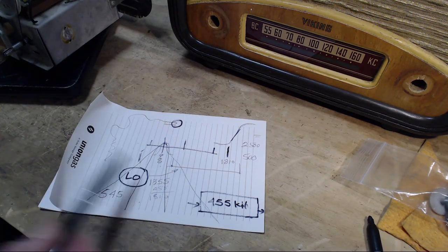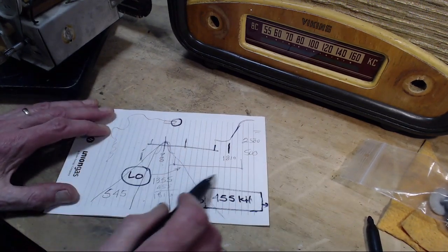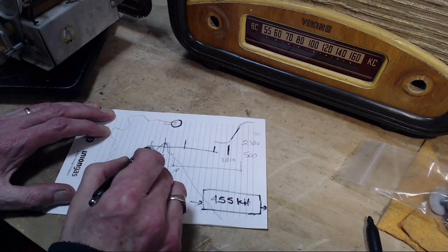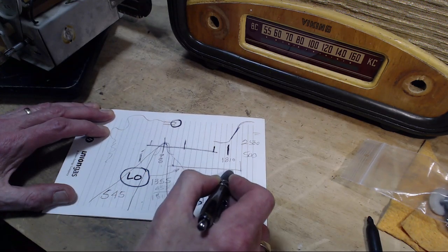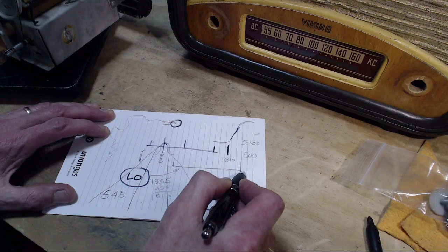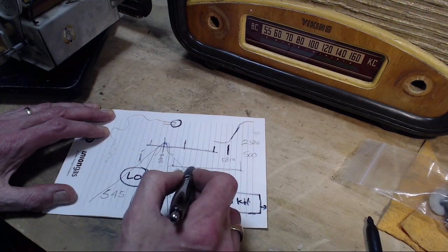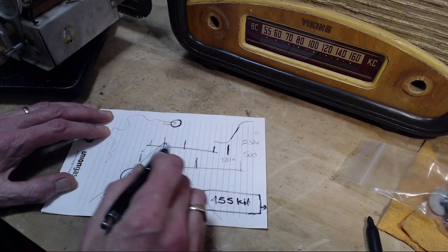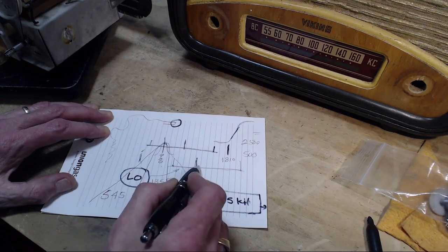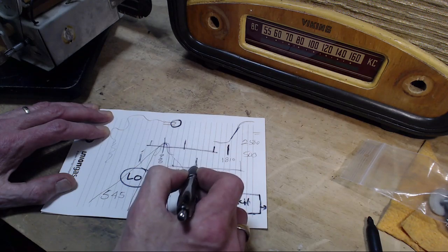Now, what was I going to do with this? There's a couple interesting things here. The radio's reception range overlaps with the local oscillator. So you could potentially have a radio with a local oscillator running here, because you're listening to something on your radio. Another radio can pick this up directly, can tune right here and hear this thing.